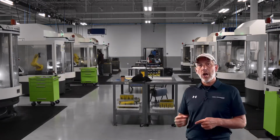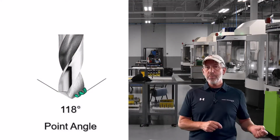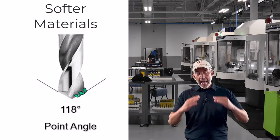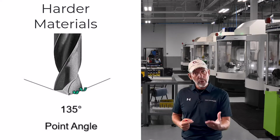So if you're looking at a 118-degree point angle, it's more for general purpose, more for softer materials, 1018s and stuff like that. As your point angle gets flatter, then it's going to be for harder materials or materials more difficult to cut.